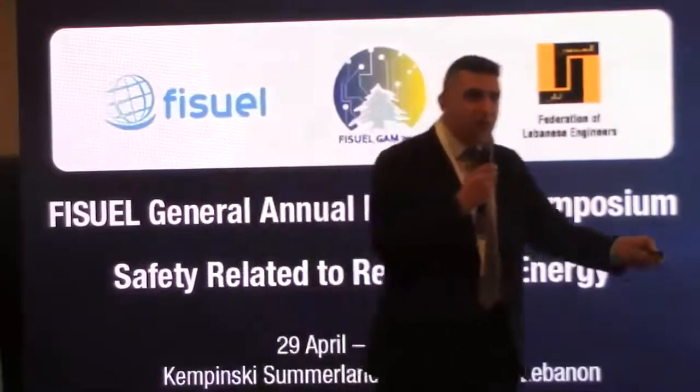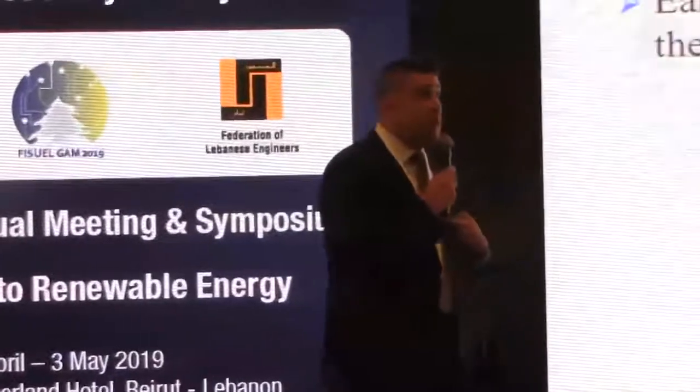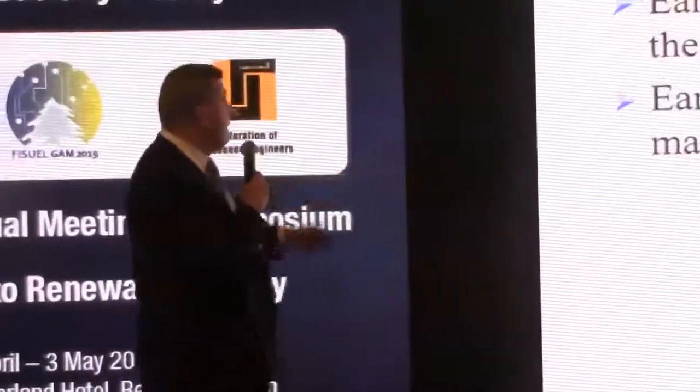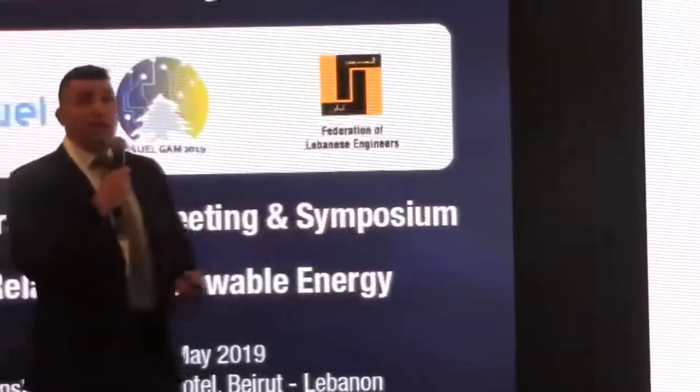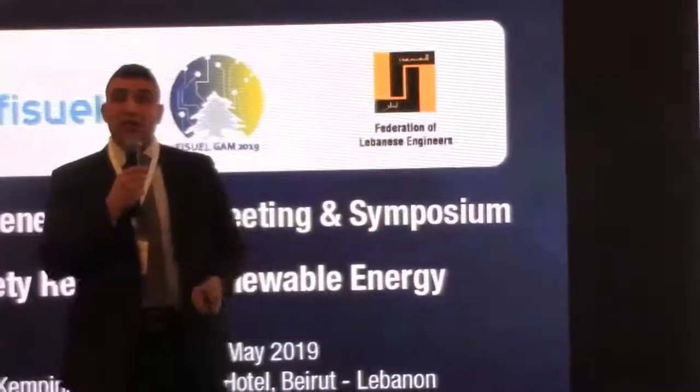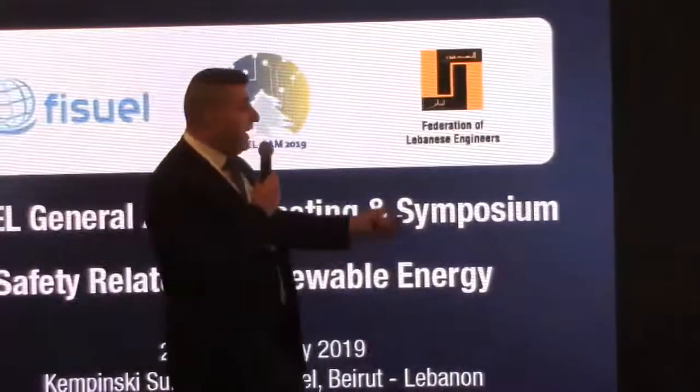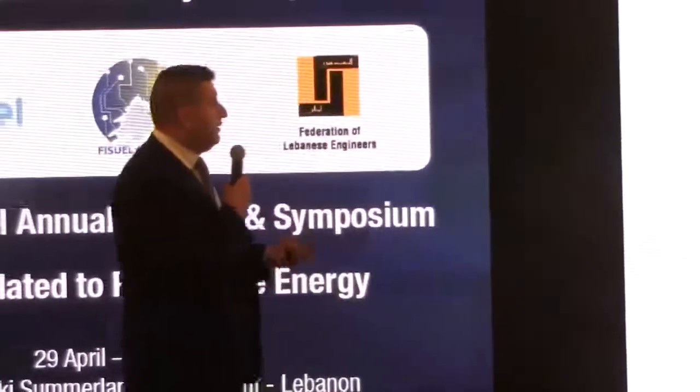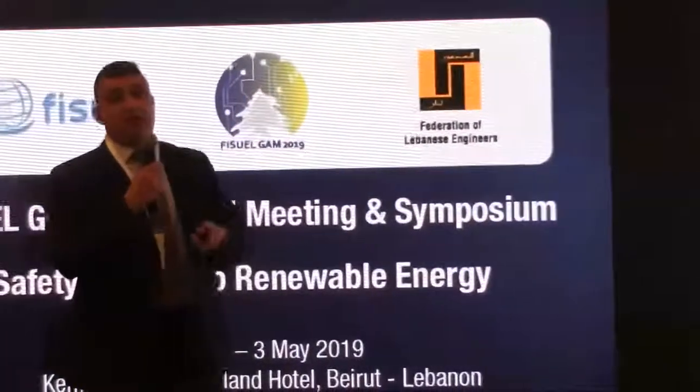And based on my surge voltage, we'll see if it complies with my insulation level that has been designed. The earth grid can be made by a single electrode, multiple electrodes, or could be made by a combination of a mesh and an electrode. Now, it's very important for us to notice the following 2 equations.